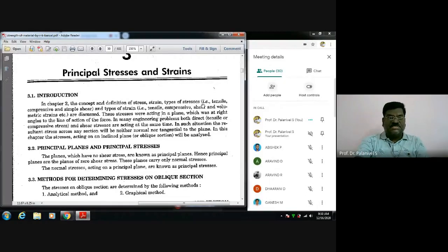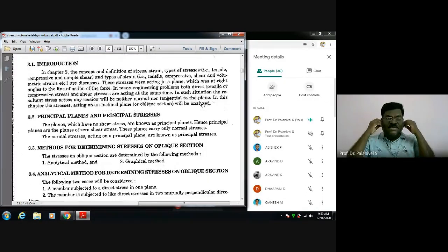No problem, just listen. Principal planes and principal stresses. What does principal plane mean? The planes which have no shear stress are known as principal planes. Hence, principal planes are the planes of zero shear stress. These planes carry only normal stresses.